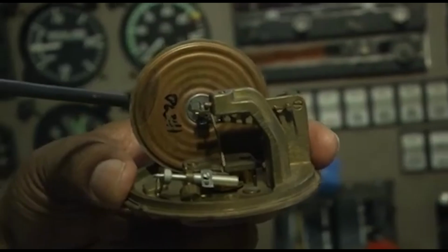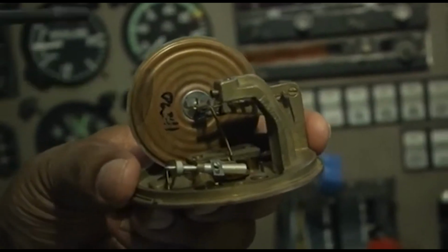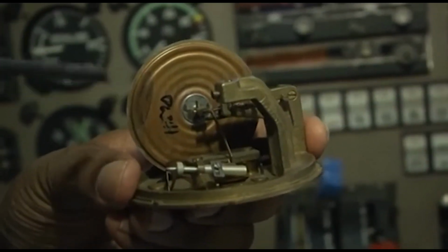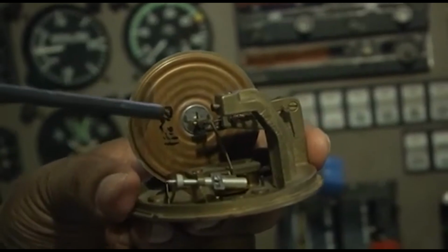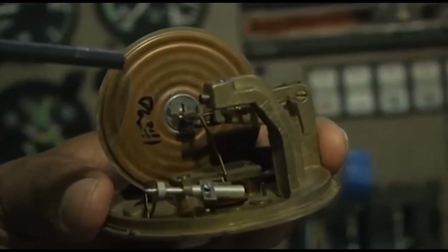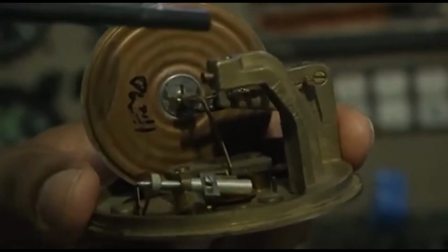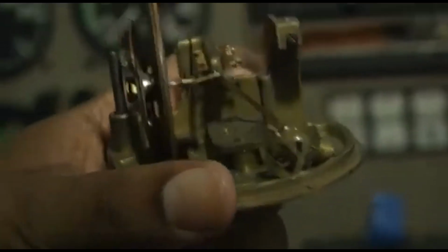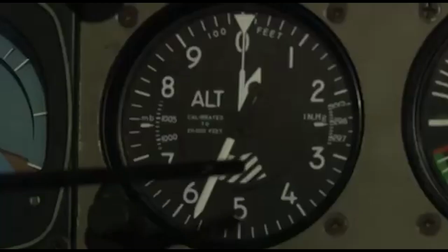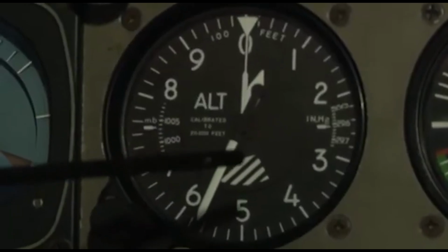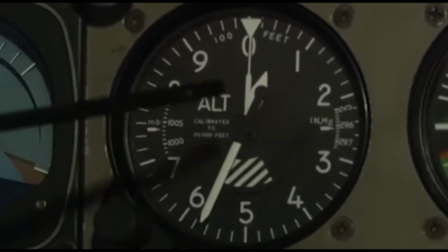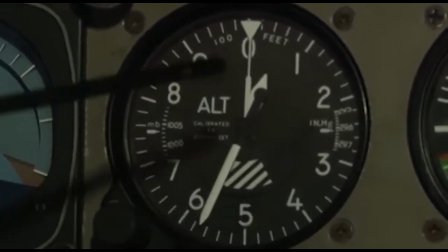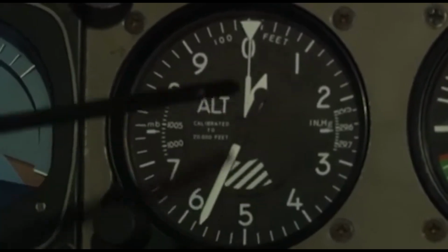This movement of the capsule is transmitted to the arm, magnifying lever, sector, pinion and pointer. These are all the mechanical linkages between the capsule and the pointer, and the pointer finally moves over a dial which is calibrated in feet. The geographical location is not a datum for the altimeter. It is the pressure value which is the zero datum for the altimeter.